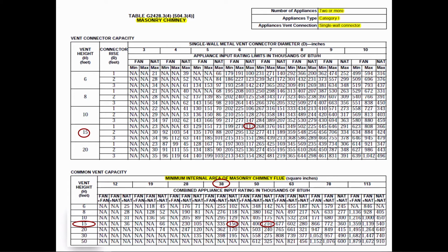There's 2 ways to do it. You can interpolate, find a value between 2 known points, like I know 15 and 20, I can interpolate and then interpolate all the values within the body of the table, or you take the next value down. If we round it up, ladies and gentlemen, we increased our capacity incorrectly in the connectors. Look at the values here. These values are in thousands of BTUs per hour. You see what we're doing?